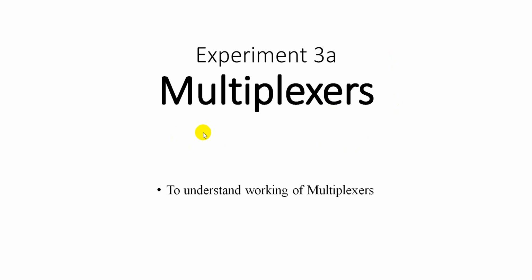Just before starting the experiment, what exactly is a multiplexer? We say that it is a combinational logic circuit whose job is to perform the selection operation. Basically, from many inputs, one of the input lines is selected and that appears at the output for you. So in the case of a multiplexer, we can have 2 power n input lines and only one output